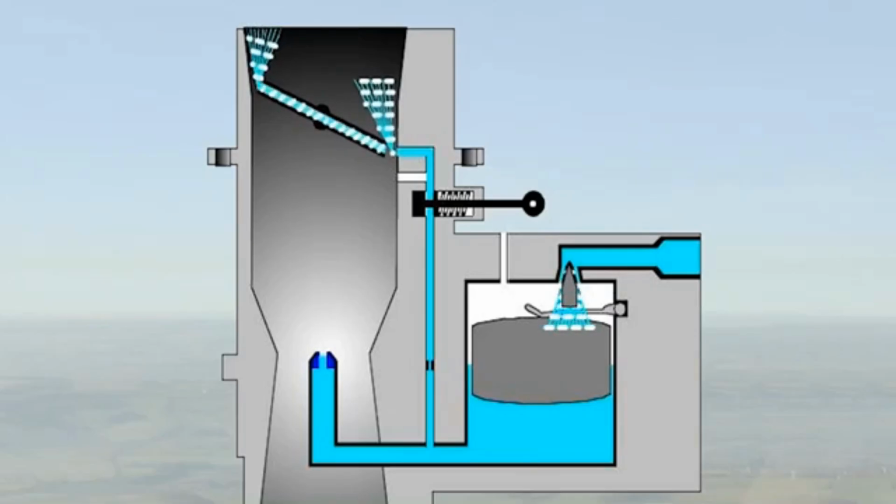At low engine speeds, the volume of air passing into the engine is so small that the depression in the venturi may be insufficient to draw fuel through the main jet. A considerable depression exists above the throttle valve, and this is utilized to effect a second source of fuel supply for slow-running conditions.